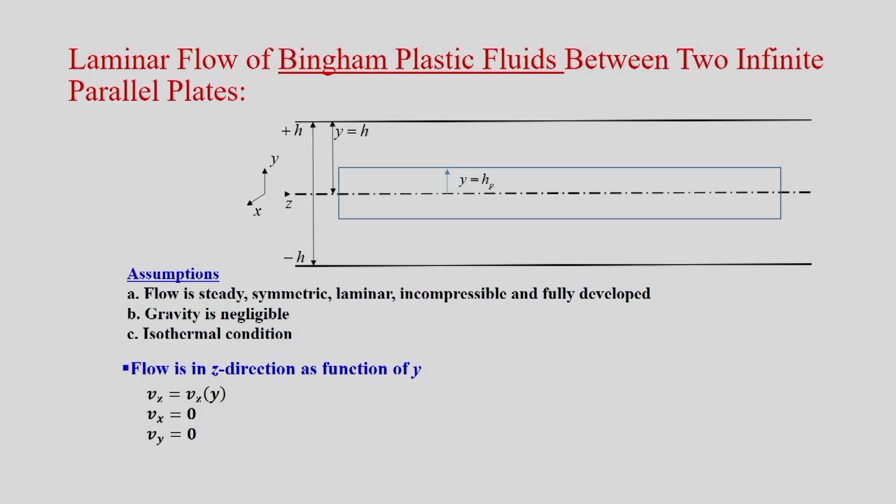Okay. So, next we take the Bingham plastic fluid. The geometry is the same: two infinite parallel plates separated by distance 2h, that is between minus h to plus h. The flow is symmetric, so I can take only half the domain, that is y equals 0 to h, and do the analysis to get the required answers.